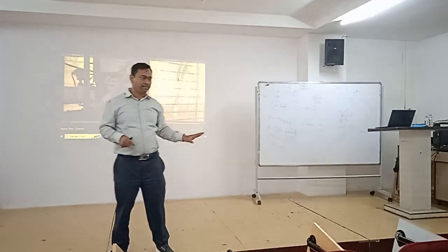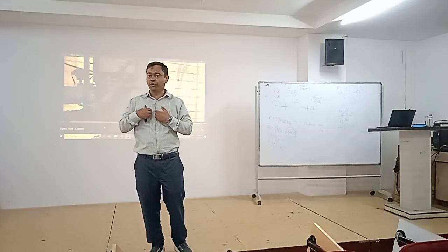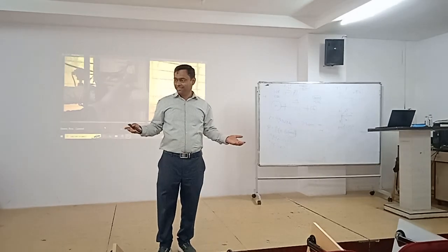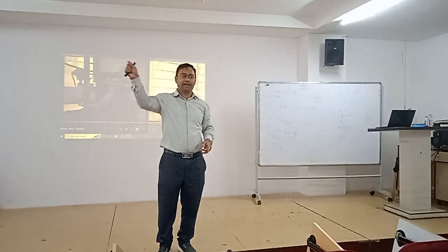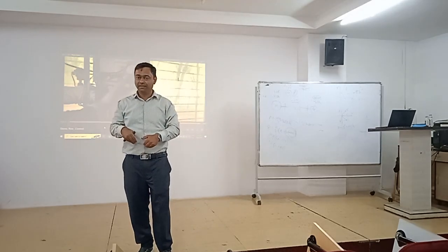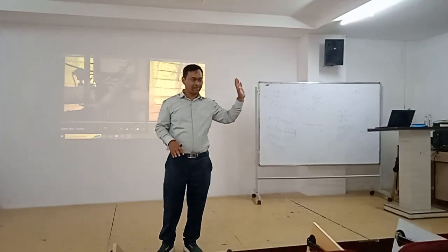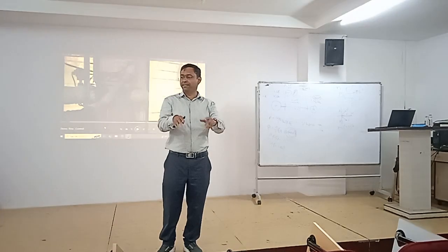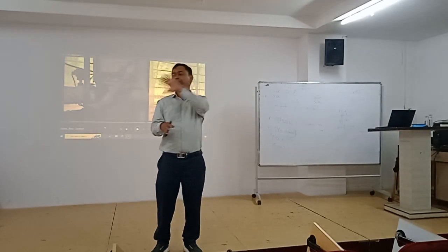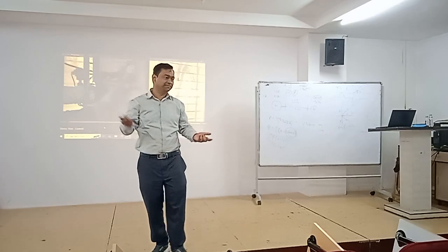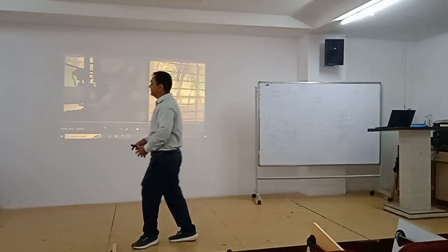To take another example, here we set the flow of 50. 50 was what? Actually, it is the desired value of output. We want flow to be 50. That's why we set 50. Suppose you go to a petrol pump, suppose we want petrol of 5,000 rupees or 2,000 rupees. Then that person will set 2,000 rupees because we want petrol of 2,000 rupees. So the desired value of output is basically your input to the closed loop system. Correct? And whatever control strategies are there, they are actually maintaining both only. Whatever may be the input, it will try to make output same as that of input. Both should match. Correct?